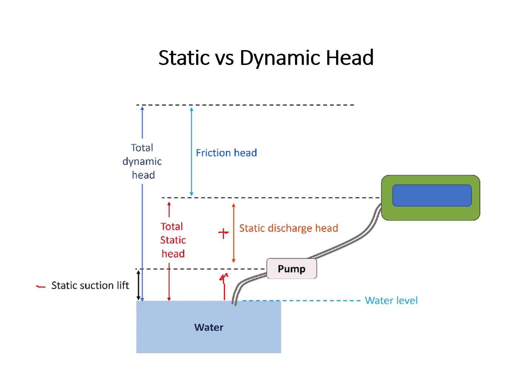And if you want to talk about the dynamic head, it adds the fight against friction. So all frictions will be accounted for by the dynamic head: frictions from the pipe roughness, from elbows, from fittings. Mastering this helps you size the pump and save energy.